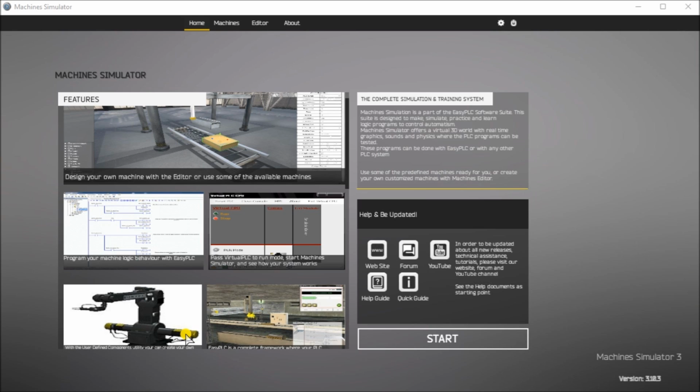When the start button is energized, it will fill up a tank until the lower level sensor is detected. The mixer blades will then turn on until the top sensor is detected. The tank is then drained past the lower sensor and the process repeats 3 cycle times. Once the sequence is complete, the tank is completely drained and ready to start again.